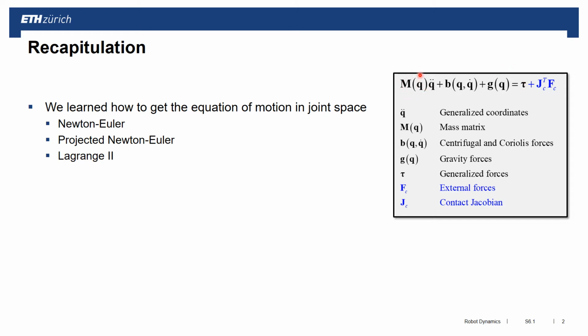We have mass matrix times acceleration plus Coriolis centrifugal part plus gravity part equals the actuation torque. Now what is new and what will be used also in this class is, in case you have external forces acting on a system, in that case we call it contact force, they interact through a Jacobian at that point where they act, with the Jacobian transposed onto our equations of motion.